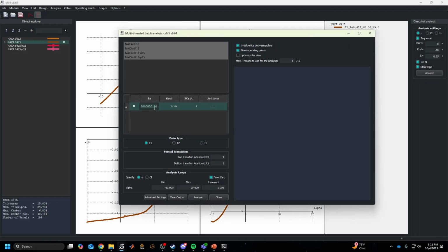So let's go ahead and start at a low Reynolds number, just so that we hit those far extremity points, so that it is able to interpolate if we have any points there. So we're going to start at a low Reynolds number, which is 100,000. And remember, our Mach number here is 0.055, so let's go ahead and throw that in. Keep your N-crit at 9, and then hit insert after. Now we're going to have 100,000 space and go to 200,000.